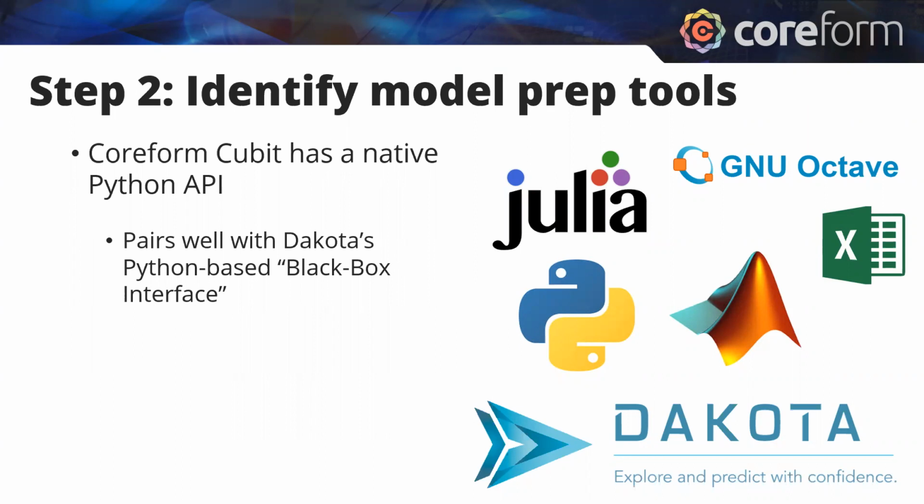Now, Dakota is an optimization framework, but also for automation. So if you want to run a design of experiments, you can use Dakota to set up and communicate through Python to Coreform Cubit, and then whatever your solver tools are, with the parameters that you want for a current study. You can set it to automatically execute, maybe off to your HPC system, or run locally. I actually did my graduate thesis using Dakota, and it's a great open source tool for that.